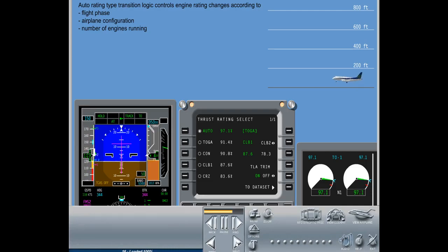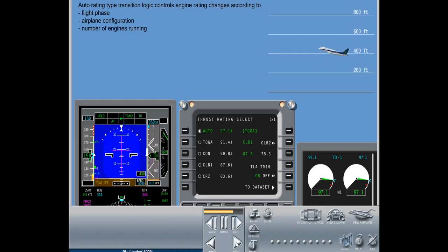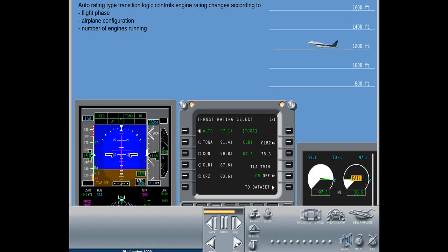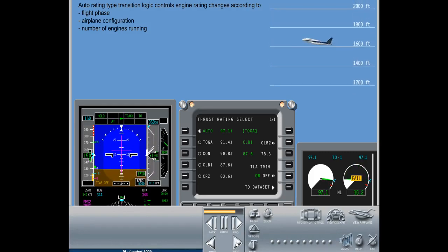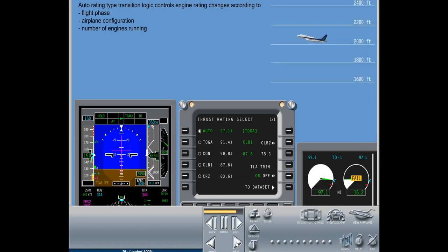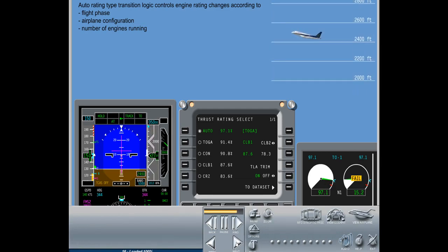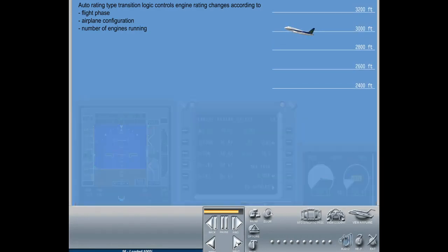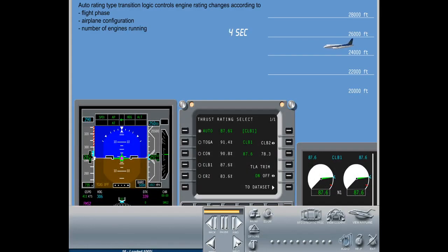During a one-engine inoperative condition, the engine thrust rating changes from takeoff to continuous at 3,000 feet pressure altitude above field elevation. The active TRS flight phase is set to cruise when the airplane is in the air and the baro altitude is between 100 feet above and 100 feet below pre-selected altitude for more than 90 seconds.